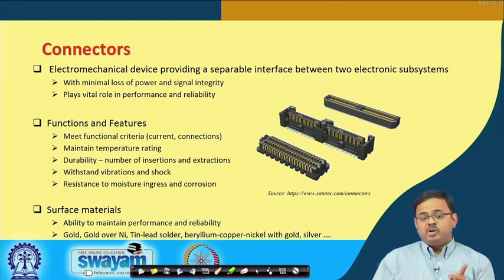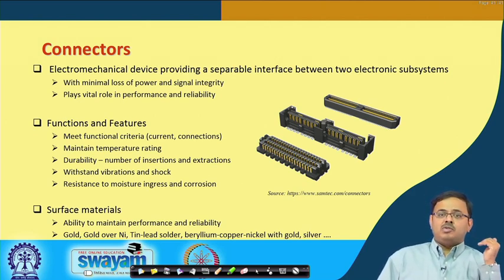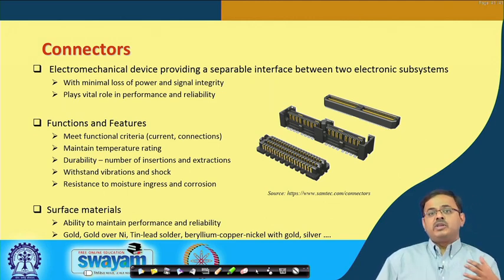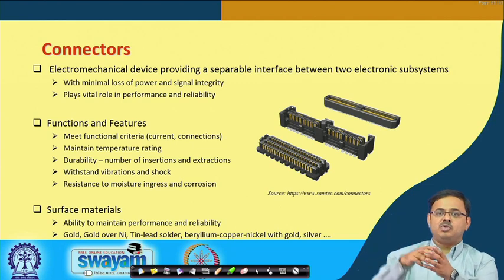Okay. It should be able to withstand vibrations and shock depending on what you have put in. We are going to talk about vibrations by the way in the second half of the course when we talk about reliability. But vibrations is important. Vibrations can happen at multiple stages for a product. For example, if you talk about military applications, space applications, automotive electronics, there is a lot of movement and vibrations all the time, but your connector should be able to withstand. There is vibration, so this connector has become loose and then it falls off.